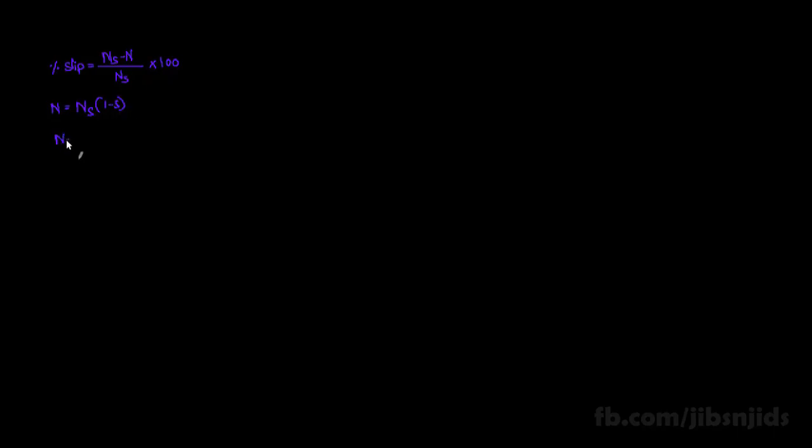Besides, synchronous speed Ns is equal to the multiplication of 120 and supply frequency, and that will be divided by the number of poles in the motor.